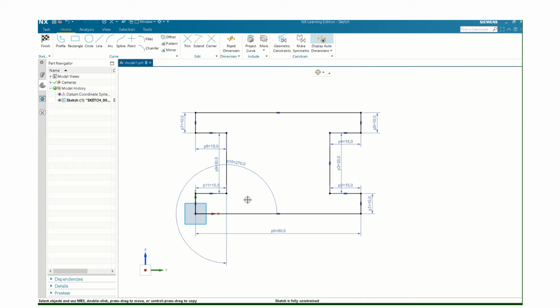It's black. I do have a cutout in the middle, and I'm going to use the rectangle tool in this case. I'll just use this one here. And be careful when you're drawing because you'll attach constraints on there. Like if I accidentally line that up, then it's going to be stuck. I'll have to break that constraint. So in this case, that's not what I'm looking for. It can be helpful, but it can also mess you up.